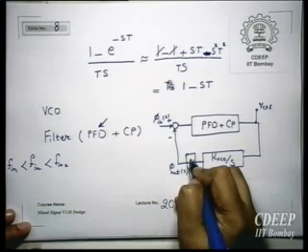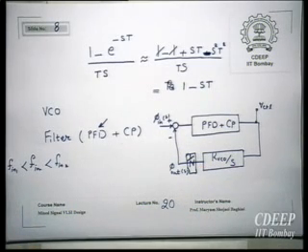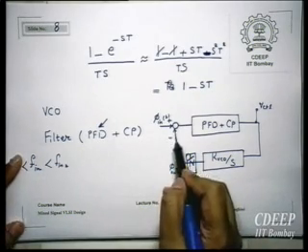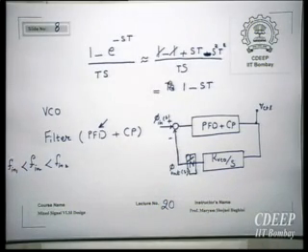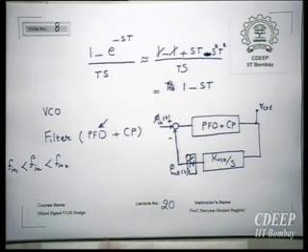This is just a divide by N. Of course, we have a frequency scalar also. So right now, this is just a simple digital PLL. So I put a counter, for example, here. I will get 1 upon N. So the input frequency has a range. I want that in that range this loop locks and operates properly.